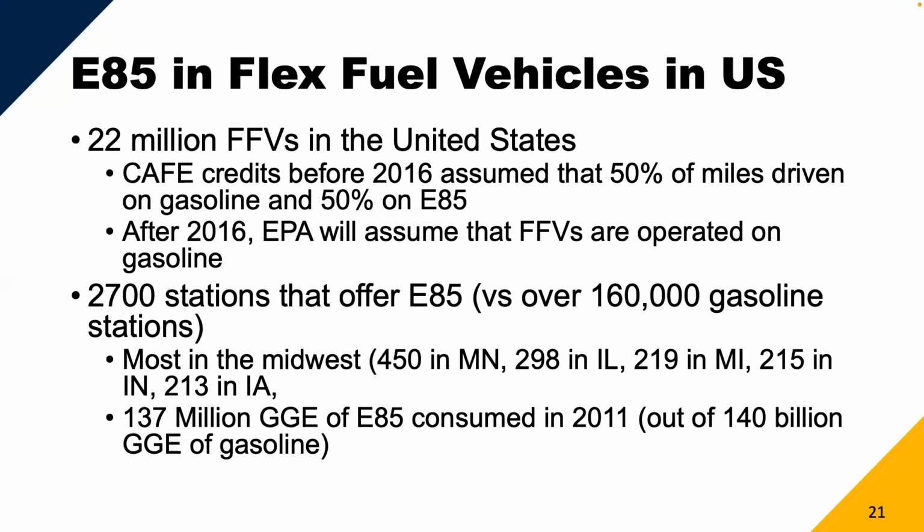A flex fuel vehicle is basically exactly the same as a gas car, except it has a couple of modifications. Like it has special O-rings that don't dissolve. A gas engine has no real issues using higher proportions of ethanol, but the ethanol can dissolve certain tubings and that sort of thing. It takes maybe about 100, 200 bucks of material to convert your car into a flex fuel vehicle.